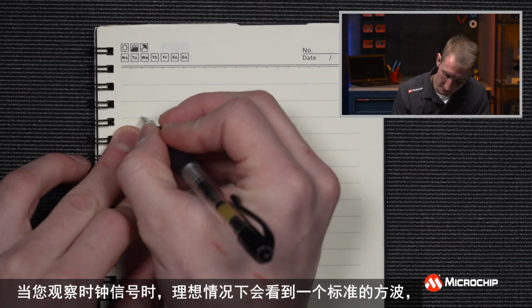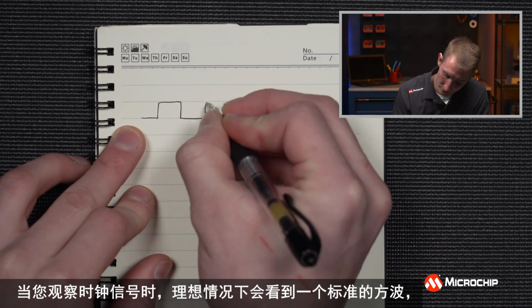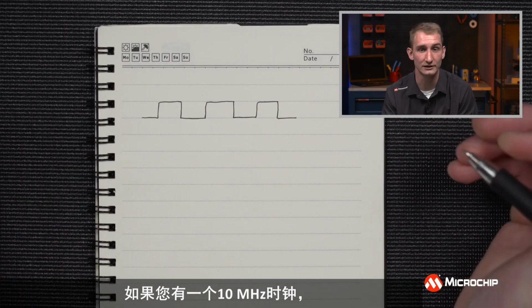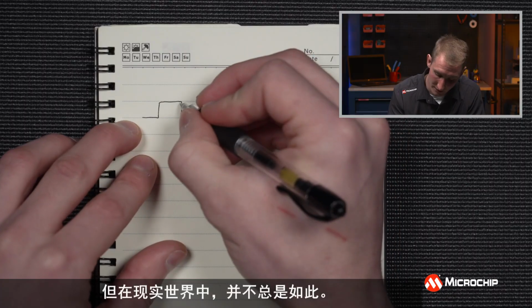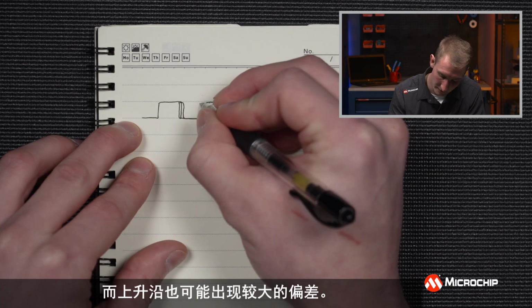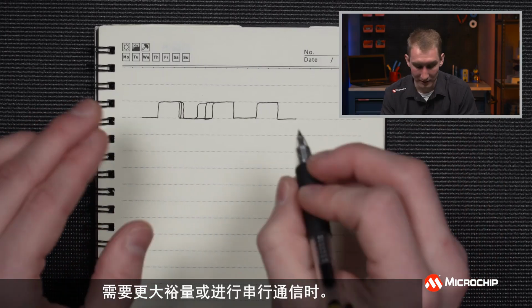So when you look at a clock signal, you'll get a nice square wave like so. And you want your square wave to always be on time all the time. If you get a 10 megahertz clock, you want it to be oscillating at 10 megahertz without a doubt. But that doesn't always happen in the real world. Sometimes your falling edge will happen a little late or a little early, or your rising edge could be way off. And that's going to create some conflicts, especially when you're working with digital electronics, where you need more margin, or when you're communicating serially. But this is only half the story.